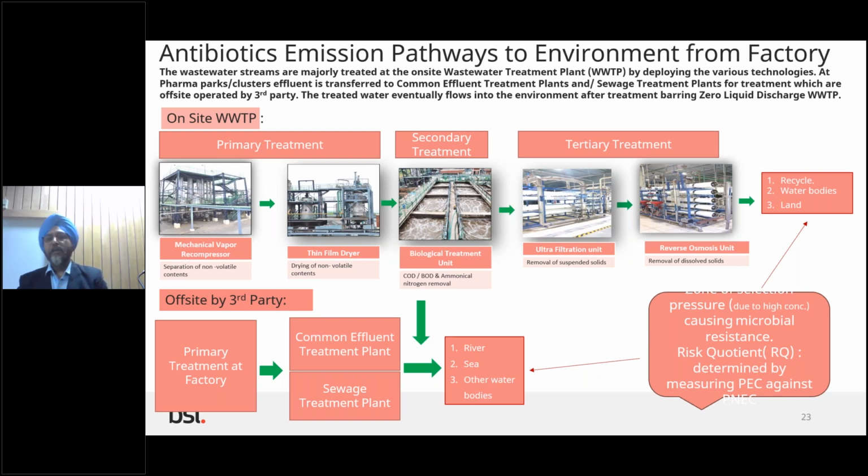We will talk later about how this standard applies to discharge to the environment. Usually with offsite third party treatment, the primary treatment is done at factory level, and thereafter, after primary treatment, the wastewater is transmitted or transported to a common effluent treatment plant.